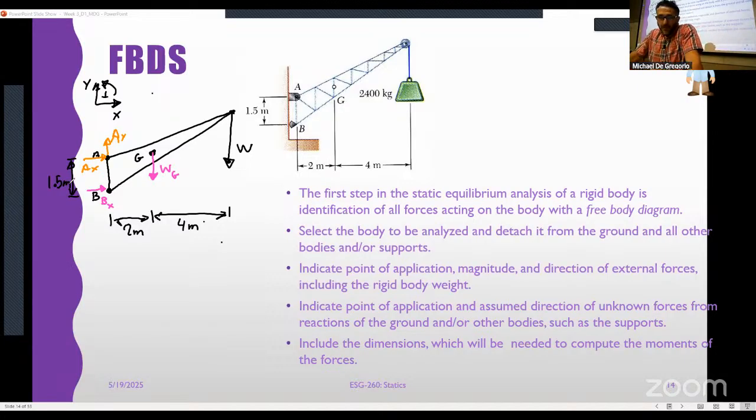I want you to notice one thing. Presumably, if we had this crane, we would know how much it weighs. We can figure out the weight of our Acme brand mast that is hanging there, okay? Because for some reason, we're at a construction site and we're trying to trap the Roadrunner, apparently, okay? How many unknowns do we have based off of these reactions? We have 3 reactions. So we have three unknowns, okay?